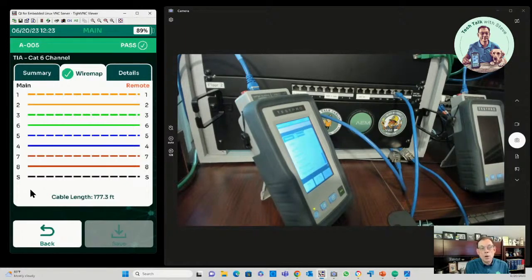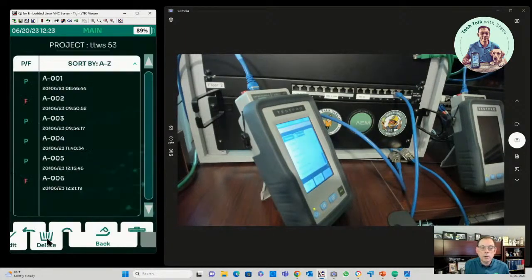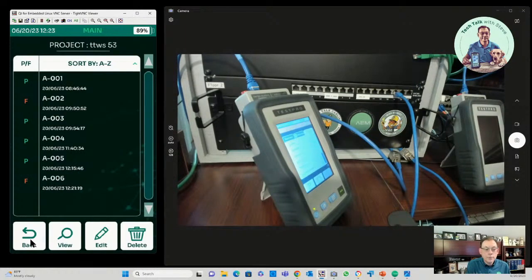And in the PC software, you have the ability to turn that on and off in the report. If it's not something that's causing your cabling to fail, but it's just alerting you that, yeah, there's a shield change, for your printed test reports, you'll turn that function off so you don't see the little sine wave in there. So it's not confusing for people. You can just turn that off. But it will show up if you want to show that in your shielding.